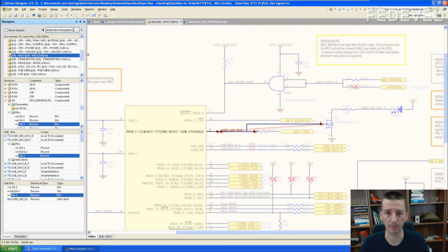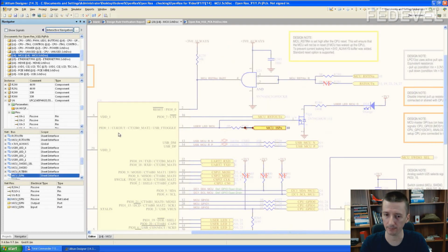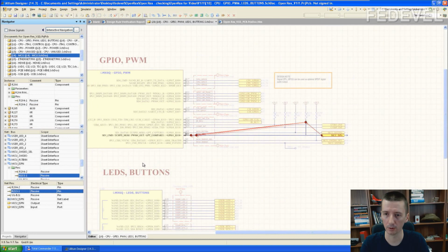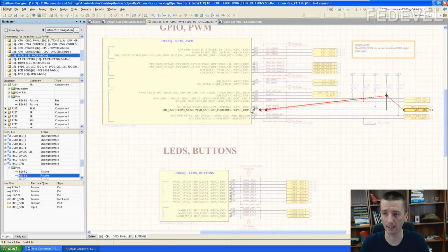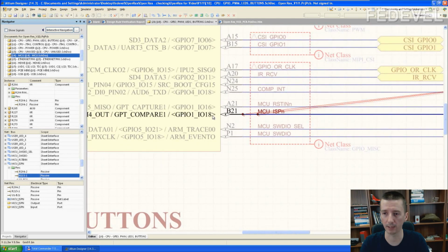And we need to follow where the pin is connected. It goes to a processor, and in the processor we can use this GPIO to set low level on the pin, so the connection is correct. What we also need to check is what is the initial state after reset of this pin, if it's input, output, if there is pull up or pull down. And also we need to check if the level on this pin is 3.3 volts. That's what we need for the microcontroller.